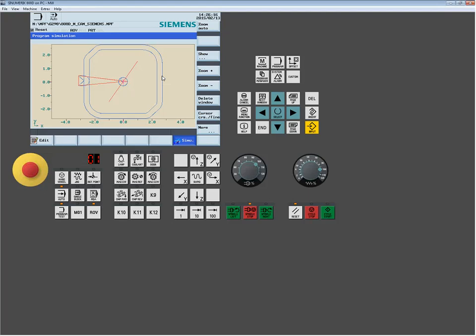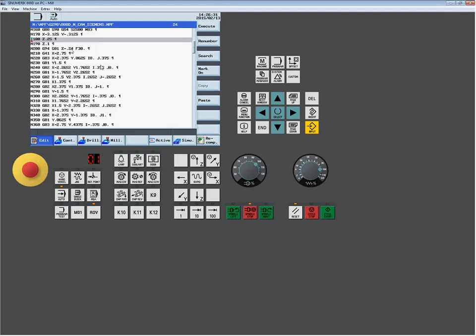Well, you got a couple different ways to handle this. Certainly, probably the most common way when dealing with programs that they want to have some ability of adjusting an offset out of the machine, it's called outputting from the CAM side, where it's still going to output a G41 or a G42. I can see my G41 is here. So there's your G41. This is what's turning on the comp. If that wasn't there, this issue wouldn't occur.